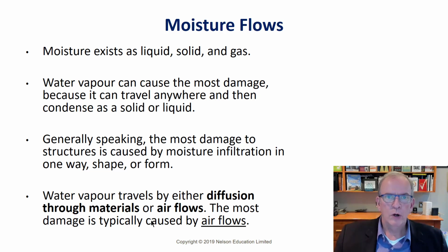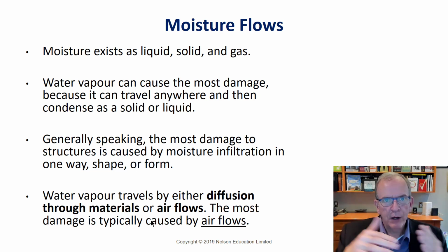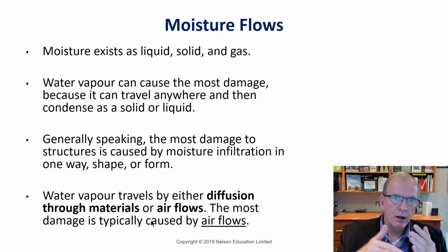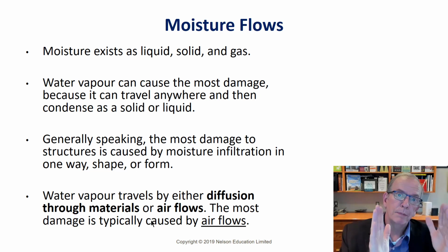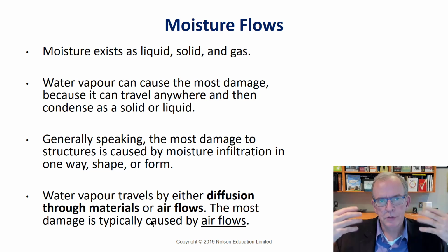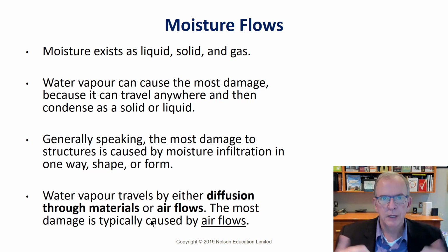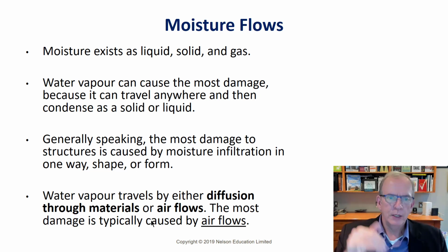Generally it's where you've got a pretty tightly sealed building, you've got a few holes, you might get a lot of moisture-laden air going through those small areas, and because there's a lot of air flowing through, it's bringing a lot of water vapor in it. And then depending on the temperature, and you'll learn more about this when you study building science in depth, somewhere in that wall, depending on the humidity level and the temperature, it'll hit the dew point and then it'll condense.